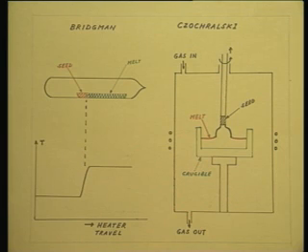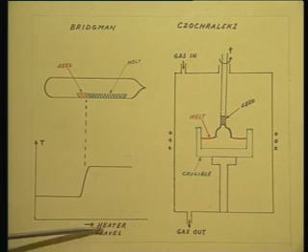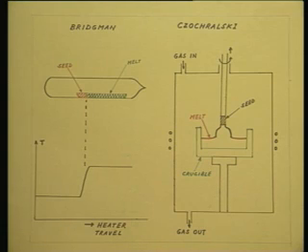This has to be very critically maintained. Therefore, the temperature profile in a Bridgman furnace has to be very accurate. Care must be taken so that the seed crystal is not molten. And then once the charge is in molten condition, the heater can be moved in this direction. What is going to happen?